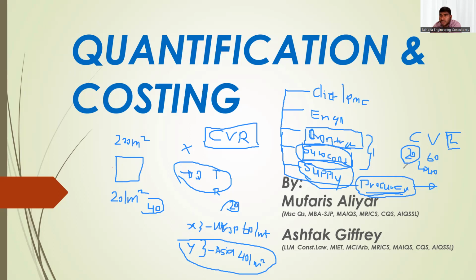As a QS, as a project manager, you have to be careful that they follow these norms. If they slightly deviate from these norms, and they are working very fast, it's no problem for you. There will be a profit for you because you are reducing the cost, since this mason is working very fast. But if they are delaying and putting in more wastage, that 20 dirham will increase to 22.